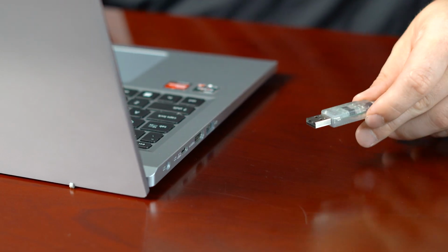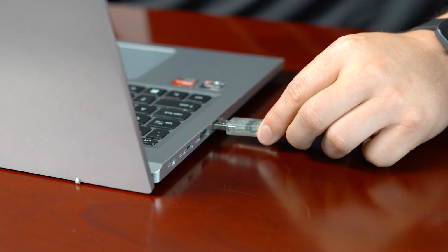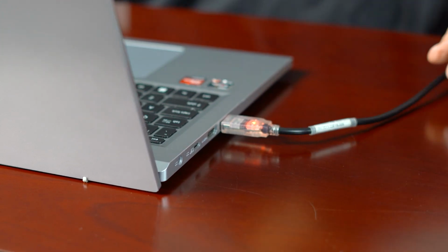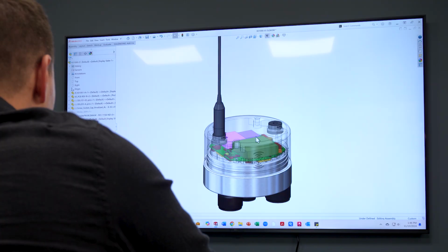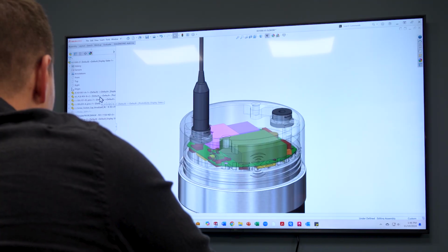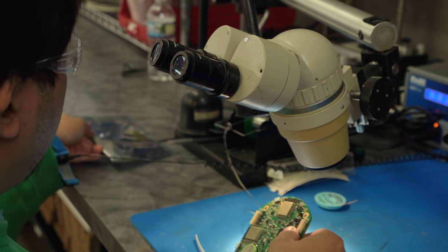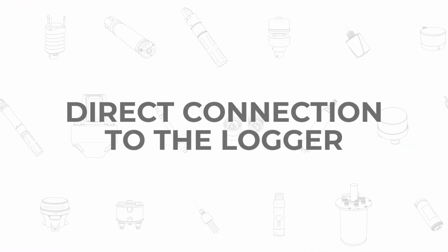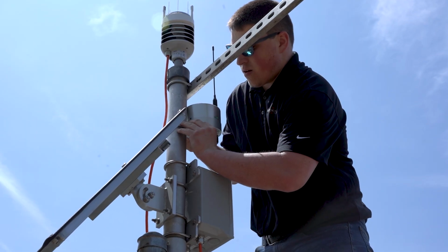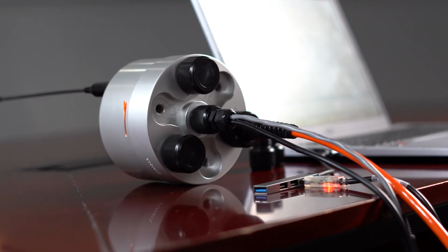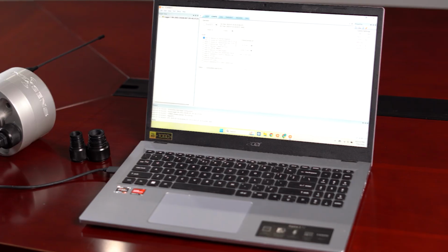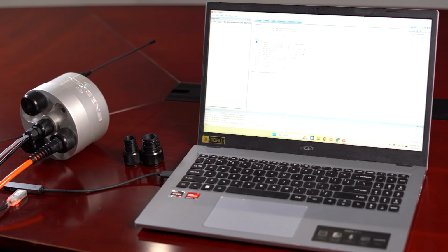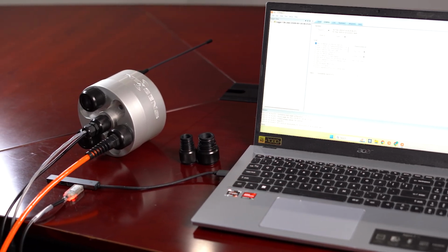Connect sensors to the manufacturer's software and confirm proper function. Another possible cause could be that the cellular SIM may have failed or disconnected. Contact NexSens or your cellular service provider. If communication has not been re-established and there are no visual or power issues, direct connection to the logger will allow users to adjust settings and, if needed, change cellular service providers.